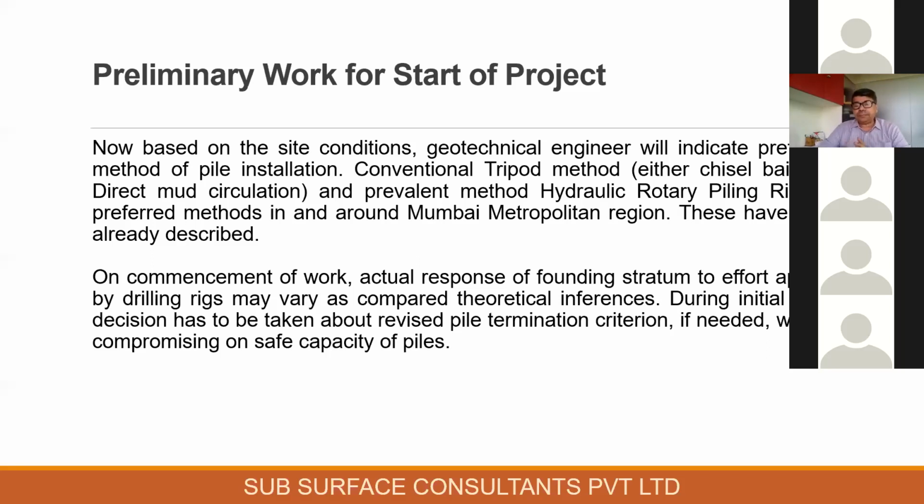Now we have gone through the steps: we have taken geotechnical data, finalized the lengths, finalized the capacities, and decided the piling machine. Now you go to site and commence the work. You will find that, depending on the quality of the geotechnical investigation data, the actual response of the founding stratum, be it soil, muram, rock, soft rock, weathered rock, whatever you want to call it, the effort applied by the machine, the drilling rig, versus the response of the founding stratum can possibly be different.